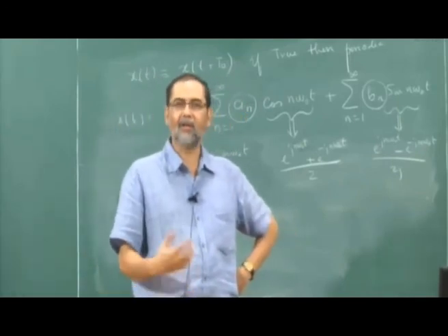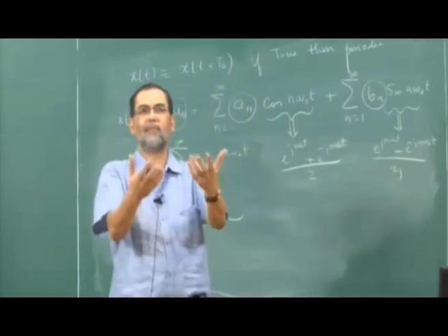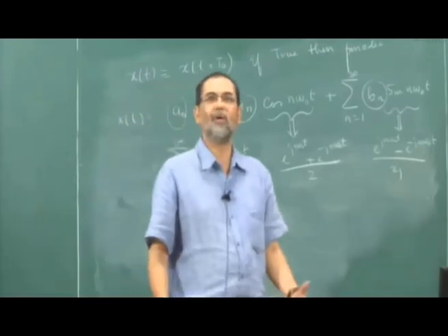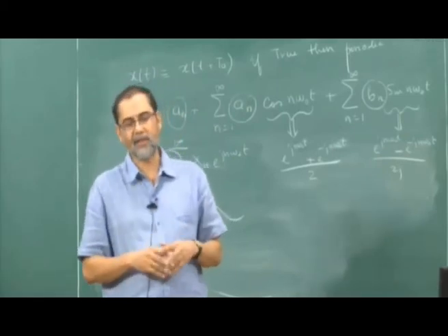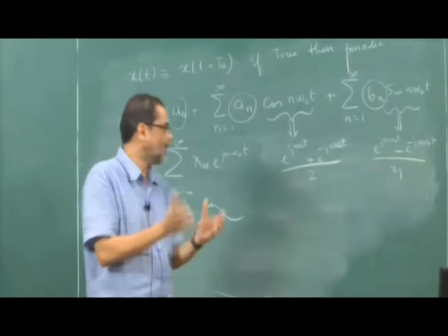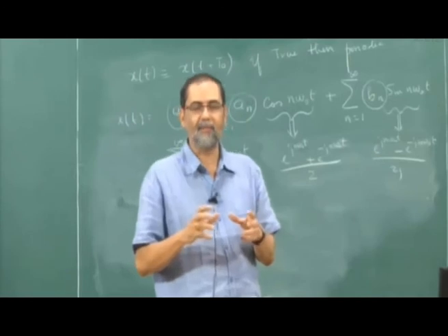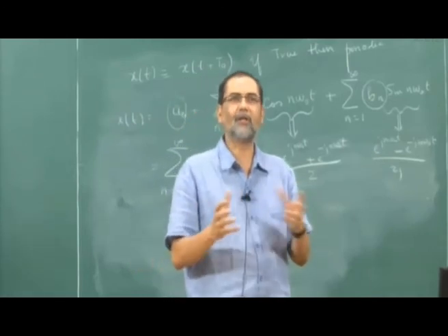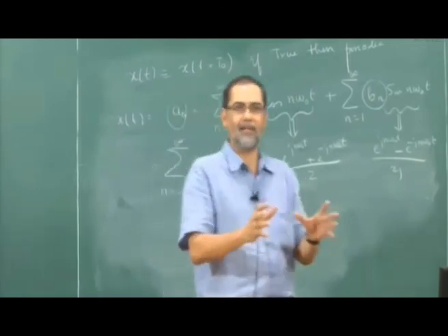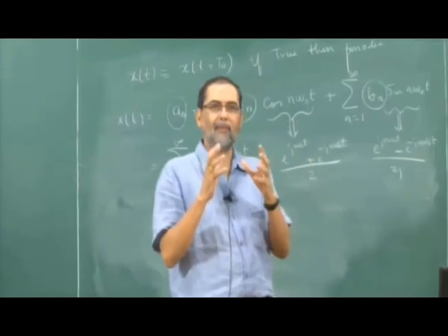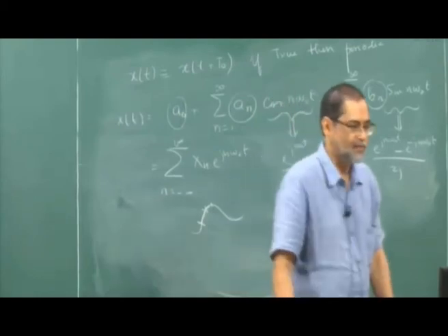Similarly, when the system is not time invariant, you can look at smaller time scales where the parameters of the system do not change. So you can have short term time invariance and linearity over a small region. It's possible to make a nonlinear system into a short term linear and time invariant system and apply this property. So yes, it's possible in many situations to use these results and apply them to nonlinear systems.